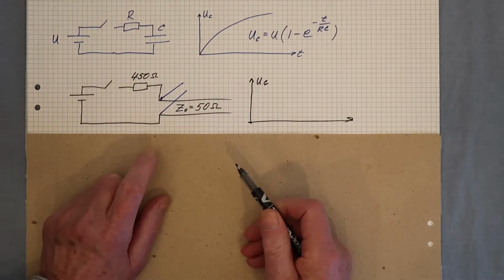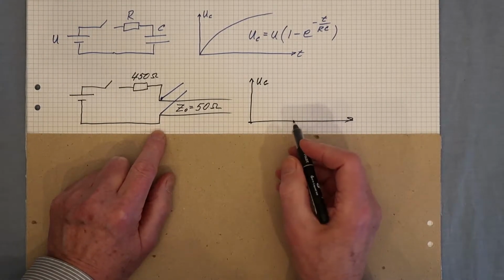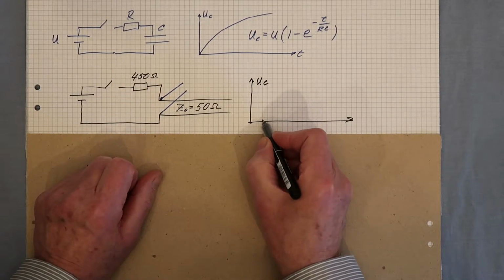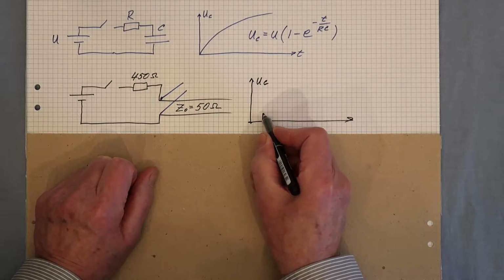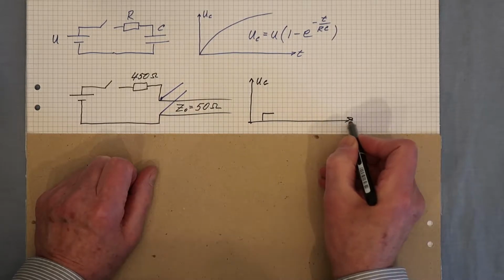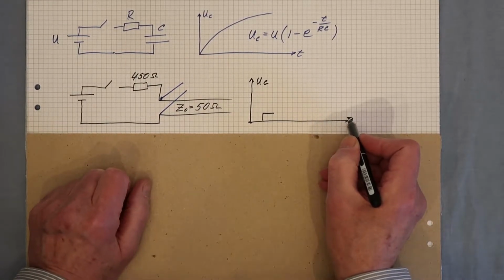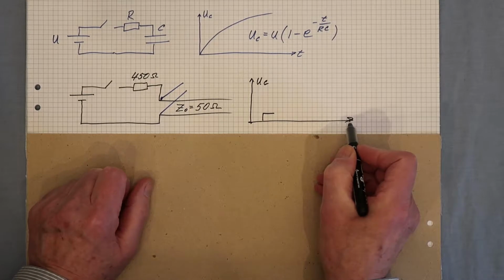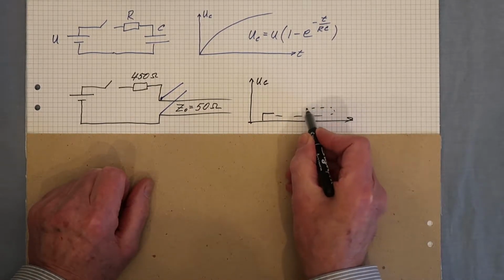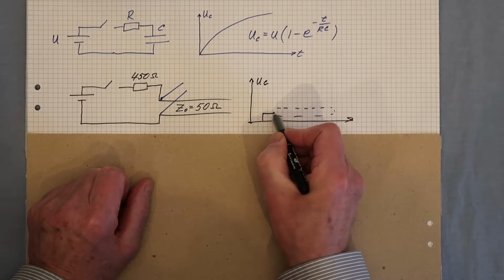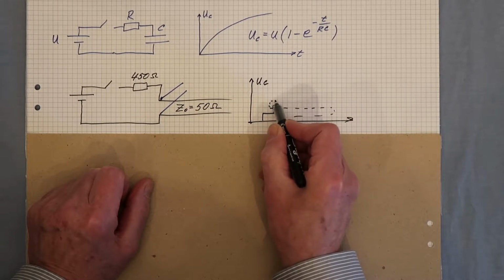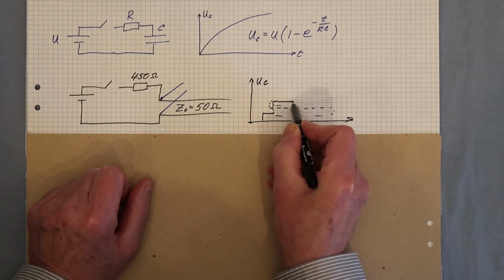The voltage here, as seen on the oscilloscope, first we had voltage division. 10% of the voltage is traveling out as a forward signal on the capacitor cable, and it's reflected back, and when it comes back, some part of this is re-reflected out on the cable.